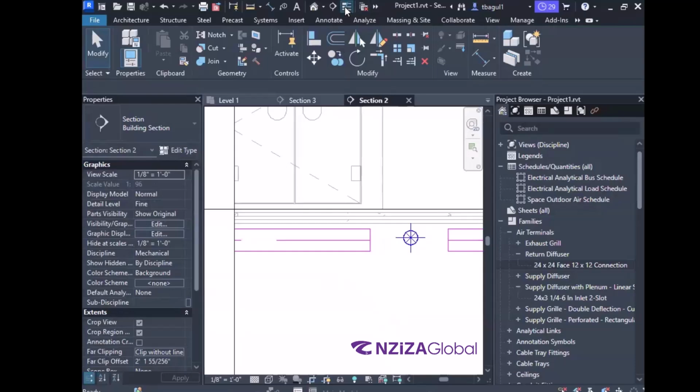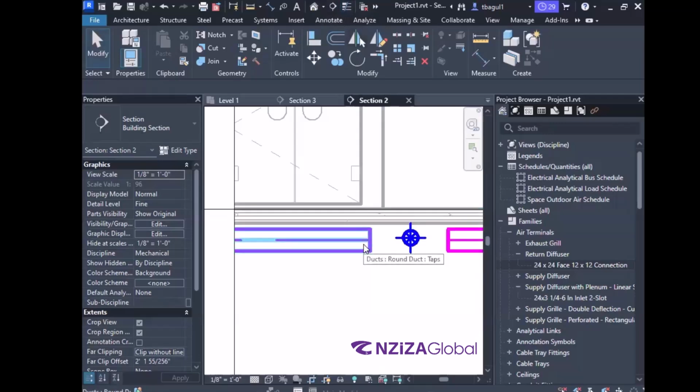But please note, if you're using this, what will be printed on your paper, on your PDF, will be the thick lines, not the thin lines. So it matters when we are doing printouts. If you're trying to coordinate something and you have thin lines, it will not be the thin lines that get printed. It will be the thick lines that get printed. So please make sure you understand this properly so that the thickness is not missed in the conversation.